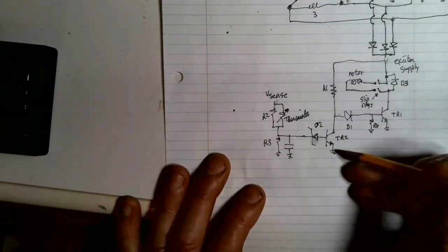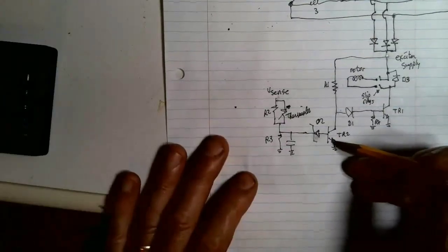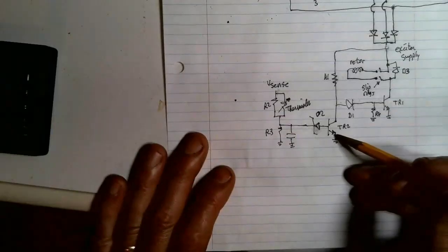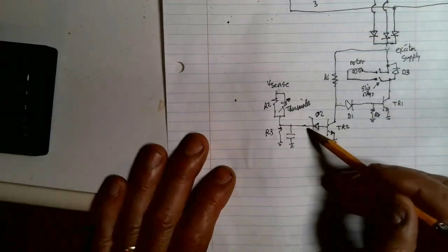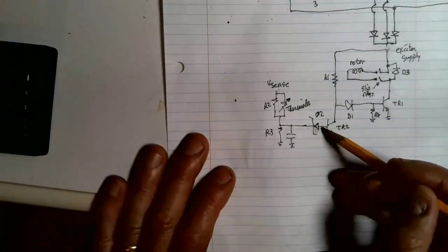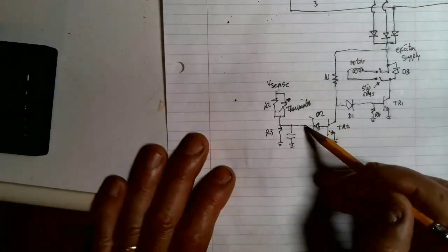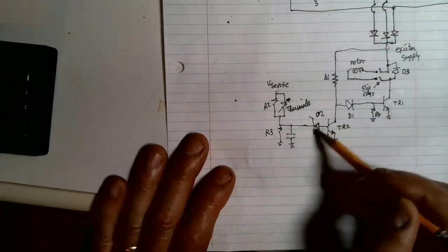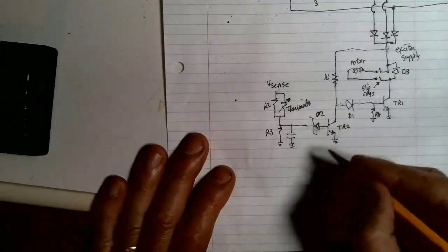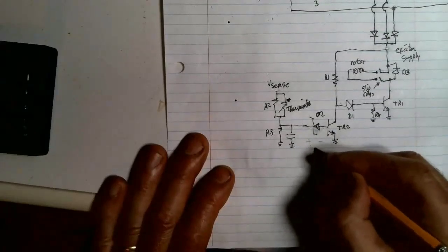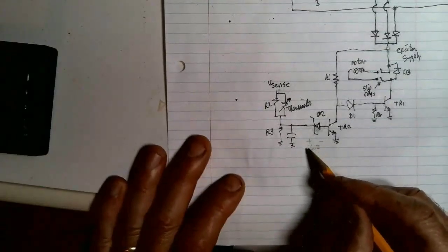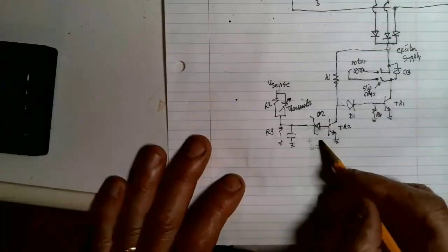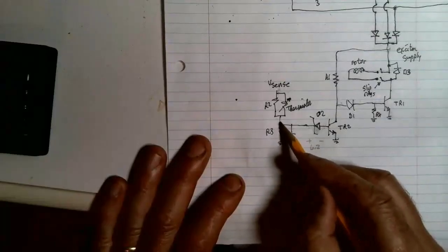Now, what voltage does that happen at? Well, it happens at VBE for TR2 plus this Zener here. There's a Zener diode. There's a real application of a Zener diode. So VBE plus VZ for the Zener, whatever that is. And I believe this is a 6.2 volt Zener, so plus or minus 6.2. It doesn't say that on the schematic, but on the internet I found someplace that said it was a 6.2 volt Zener. And then this voltage divide ratio right here.